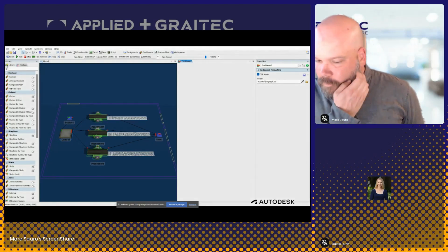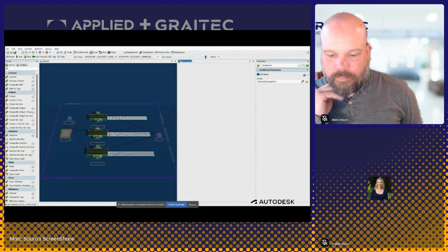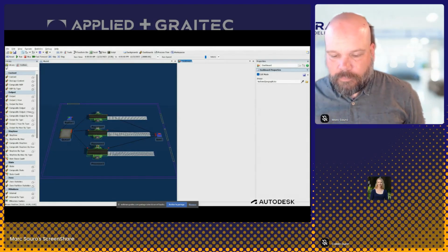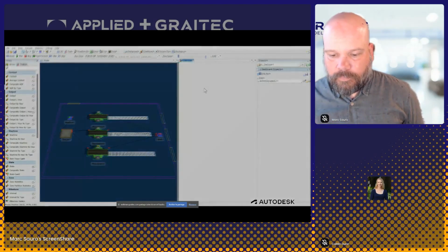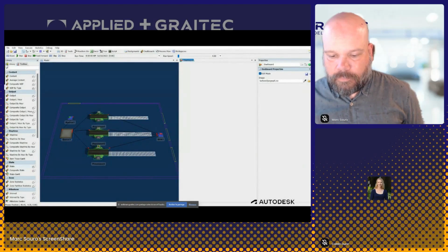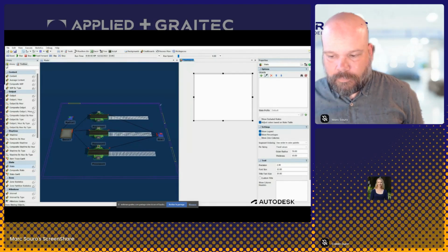There are 2 charts we want to add to the dashboard to help us understand what is happening when we run the model. The first is a state chart. Add the chart by clicking and dragging the state chart from the library to the dashboard panel, and then click on the chart. You'll see the properties of the state chart in the Properties panel. Select the picker icon in the Objects field, and then select each processor in the model so that each one shows up in the field.